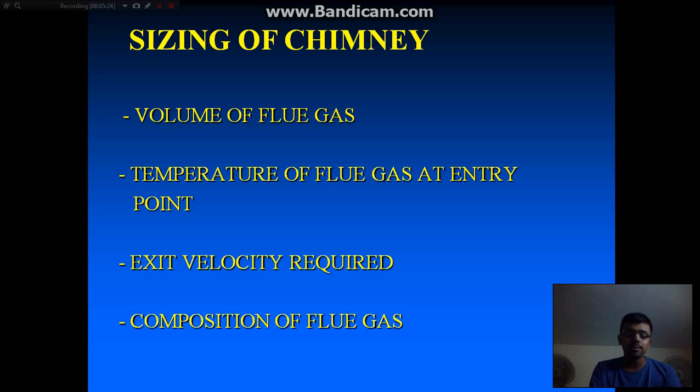So we'll be focusing on the classification based on the stacks, like the self-supporting chimney or the guyed chimney. Depending on these four criteria, the first talks about the volume of the flue gas that the chimney has to incorporate. The second talks about the temperature of the flue gas at the entry point, because this temperature also determines the sizing or the thickness of the chimney.